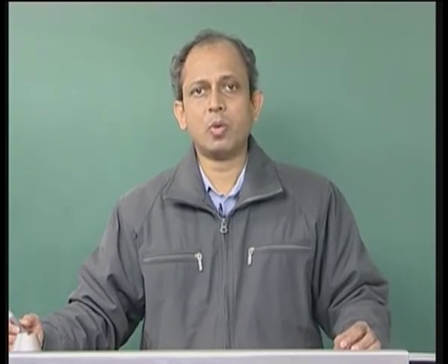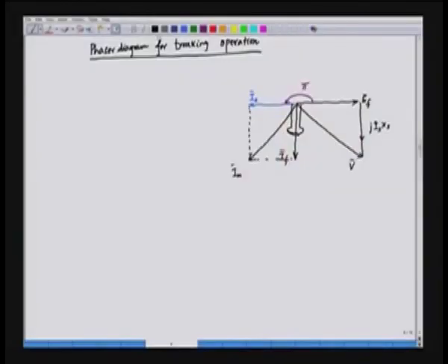Now, we have a condition in which we can also go for field weakening, which is usually done for higher speed. So, in field weakening we go for a higher value of delta prime. So, we can briefly discuss field weakening. For field weakening, the flux is reduced, or the magnetization current Im is reduced.